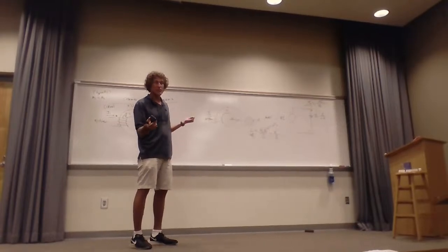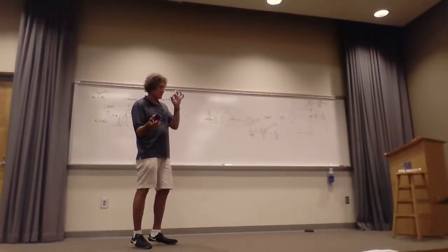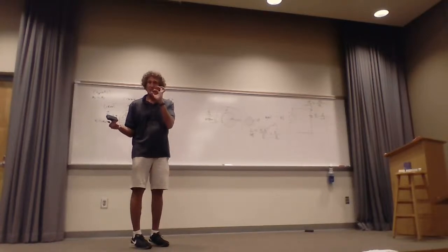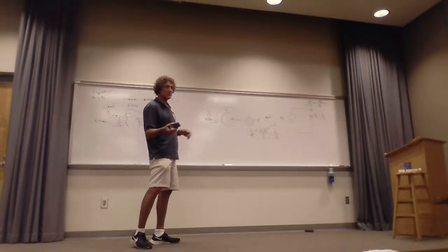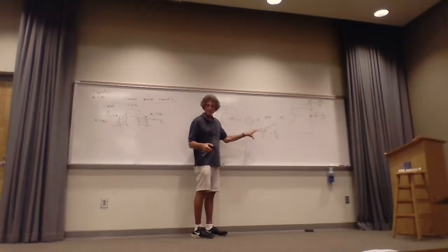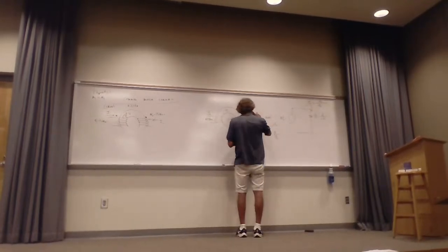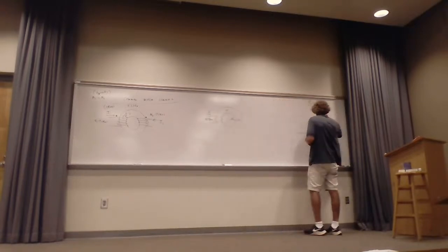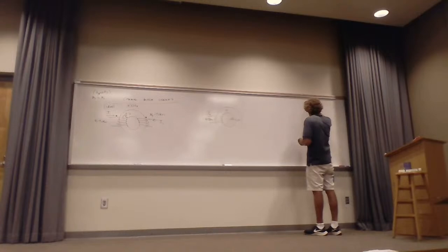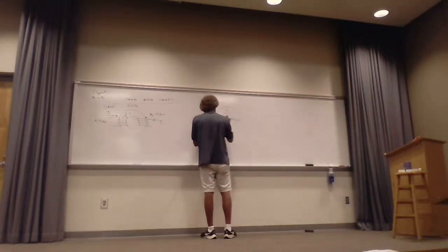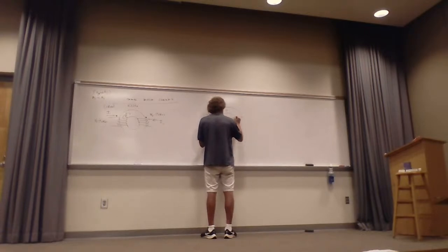Because we wind these ourselves, by the way. A lot of times we have these small little cores, ferrite cores, and we need a certain value of common mode choke. It's much easier to just wind them yourself. So if y'all good with that, right? Now, that's what happens. That's how you calculate the self-inductance. It's just N squared of the coil over the reluctance of the coil you're talking about. Now, if this is N1 and this is N2, like so.